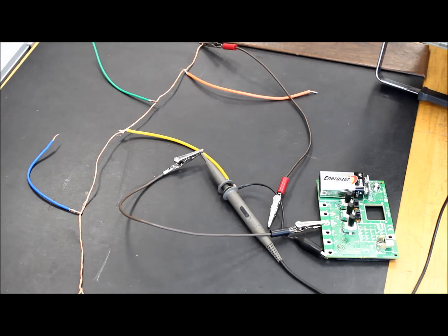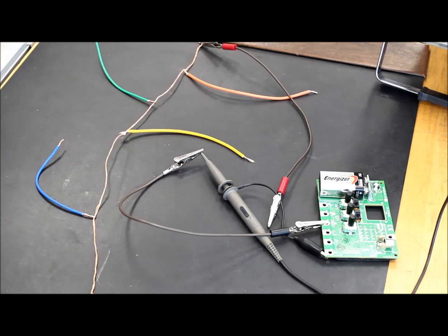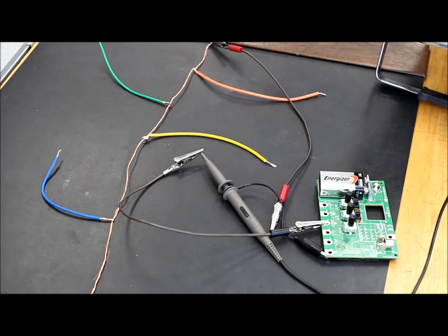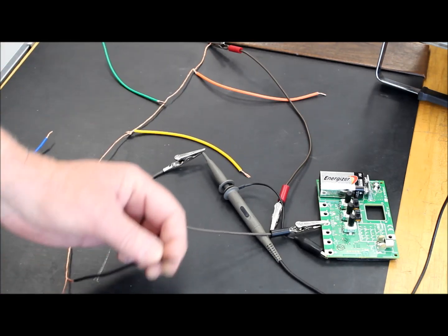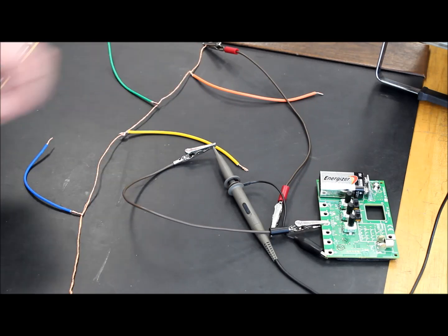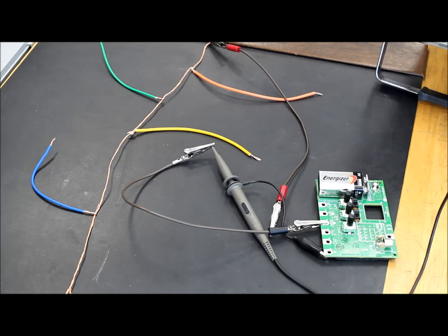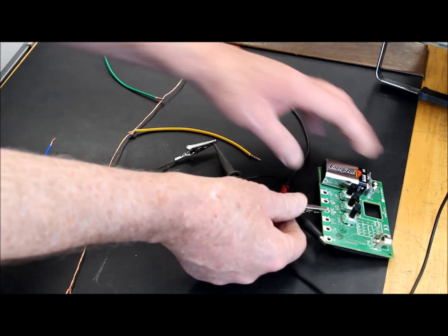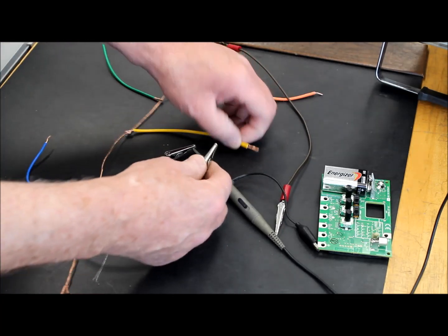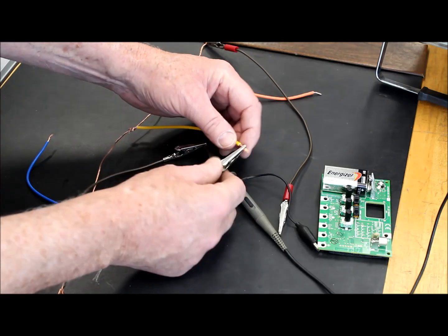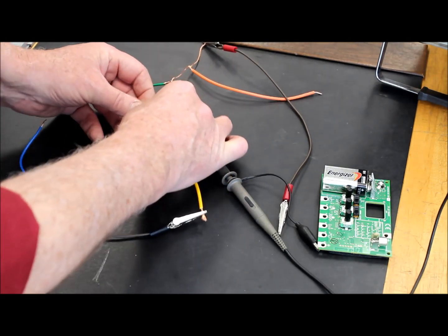So I'm going to unhook my scope lead from the signal generator and hook it to one of the nodes coming off of my bus here. So you saw before that when I put about 13.5 volts on this wire on the bus, we saw that 13.5 volts here, we saw it here, we saw it at every node coming off of that star configuration bus. They all come together to one spot. So I'm going to take my oscilloscope test lead, and let me just hook it, for example, to the yellow one here, and then we'll go back to our screen and see what we get.